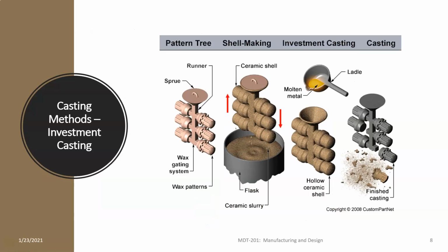All right. So how does the investment casting work? Well, you start with the wax patterns here. Okay. So all of these objects, these 6 objects right here, are the wax patterns. These are perfect replications of the object that you want to cast or create as a casting, right? They still need to be sized up slightly because we still have to deal with contraction. We can't get away from metal contracting slightly. So we have to size everything up by a small percentage so that when it contracts, we have a known size that we want. Okay. Then